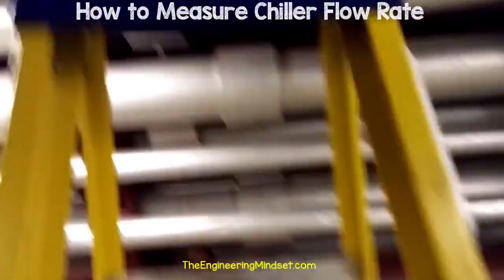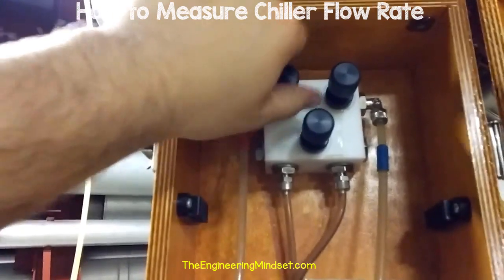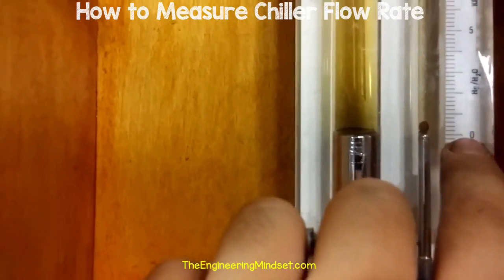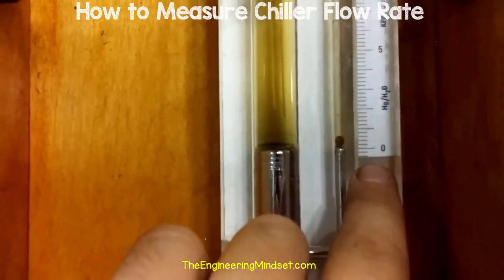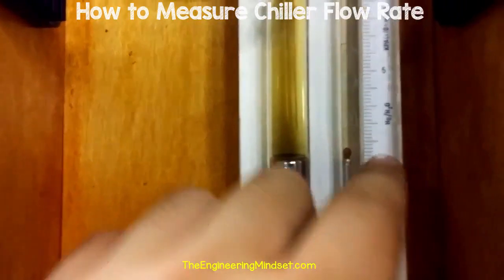Now you'll need to zero the measurement gauge, so just open up the valve on the high pressure side of the orifice plate as well as the high pressure valve in the manometer, and after that you can then check that the bottom of the little ball within the manometer is level with the 0 mark on the gauge. If it's not level with this, then you can just move the measurement gauge up or down to align this.